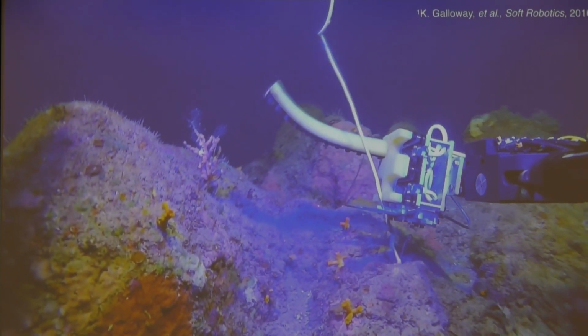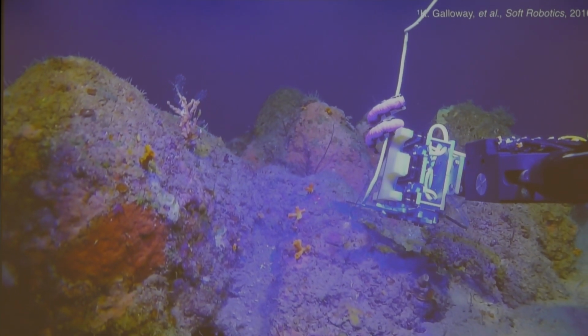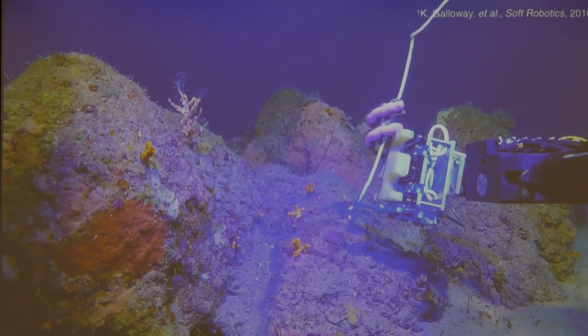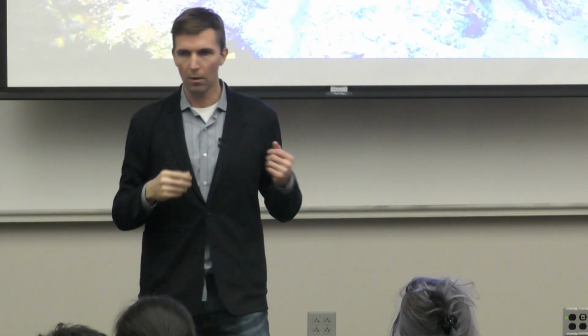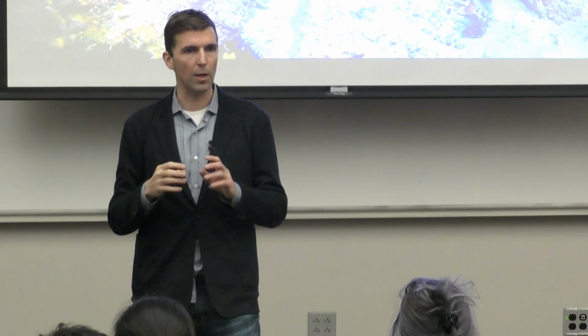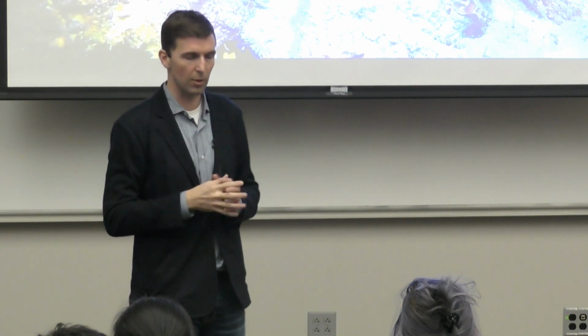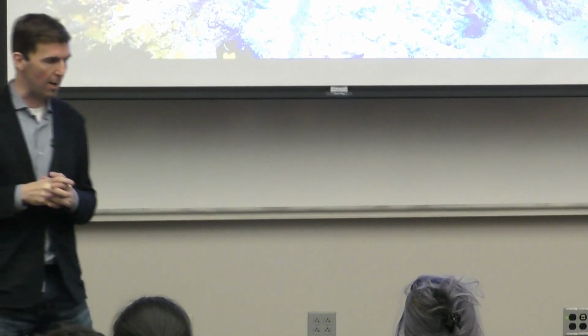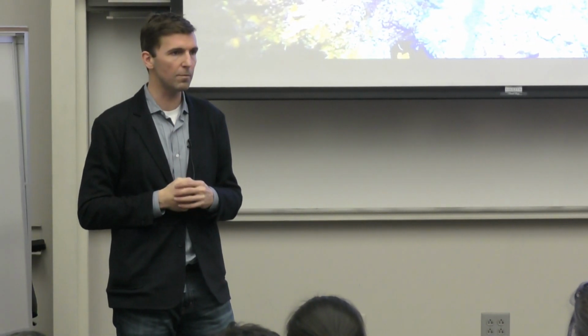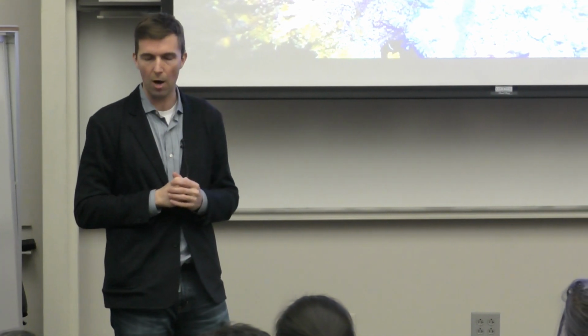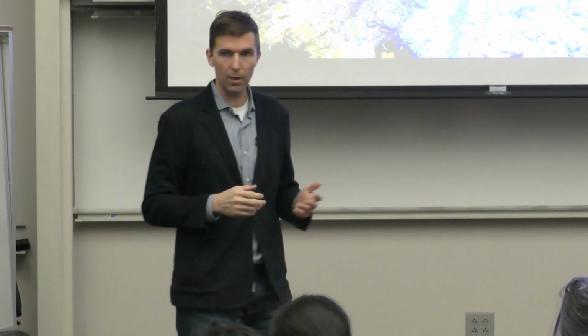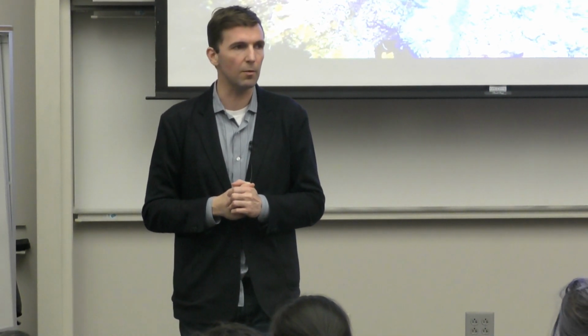So this is the first delicate grasp using what we call these squishy robot fingers. And you can imagine, okay, so you see what's just happened there. I take this actuator, I pressurize it. I'm just doing this with seawater, so I don't have to worry about any sort of hydraulic engines. I just have an open seawater engine. I'm using materials here which are totally impervious to the temperatures, pressure, and corrosive nature of the environment in which they're operating. And even if they weren't, they cost almost next to nothing.